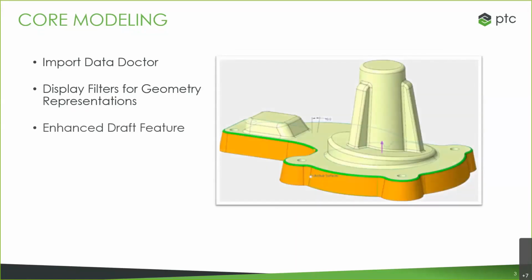We've also made enhancements to the draft feature, specifically like things around drafting already drafted features. And we also have the ability to detect existing draft angles right in the model, so it makes it very easy to work with and modify later on if you need to.